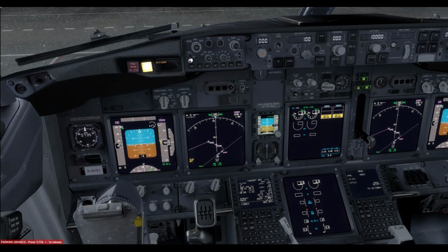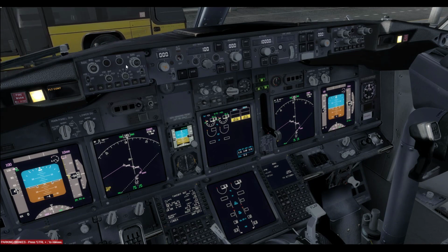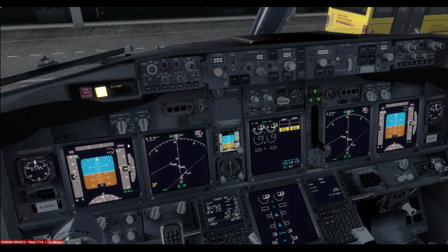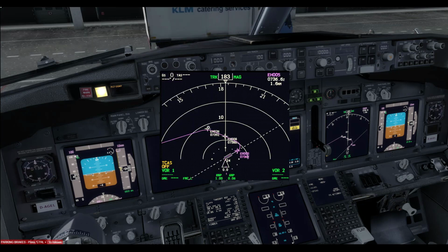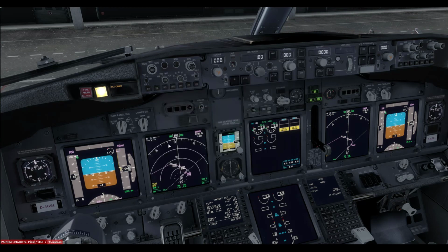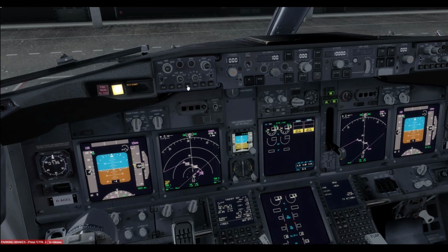Now we have to set up our EFIS displays, which EFIS panels, which are here and here. They are basically a small customization for the two main screens. So, first of all, my navigational aids, I always put them to VOR, so VOR1 and VOR2. So both needles, stick them up. The pressure in Europe is measured in hectopascal, and I always like to have my traffic monitor on and the data monitor, which shows you a few datas below the waypoints.